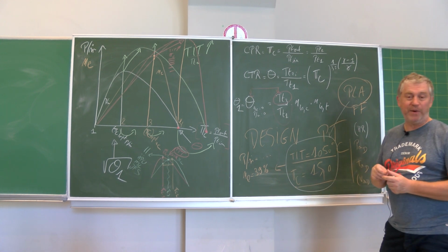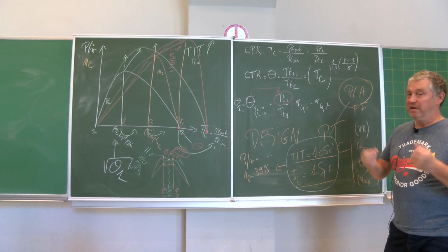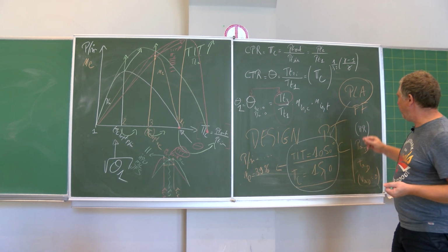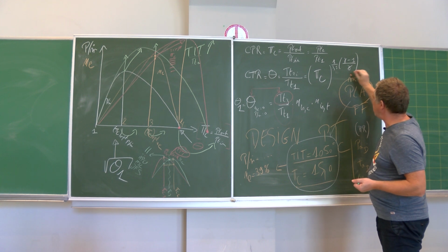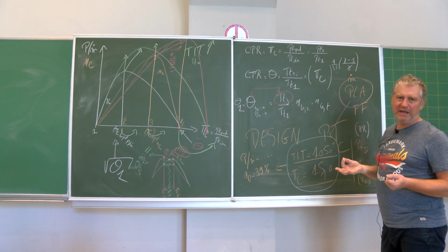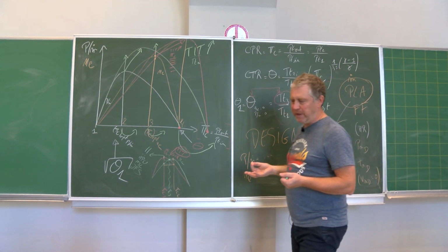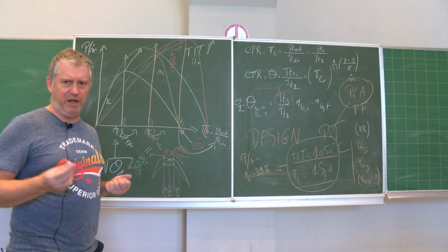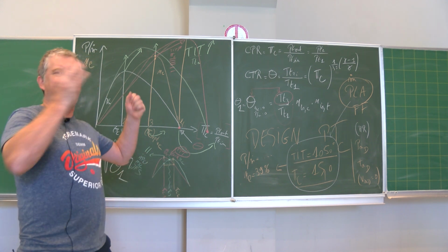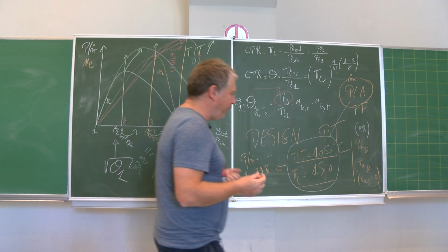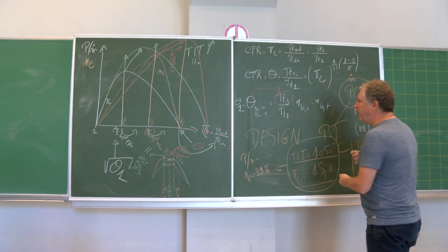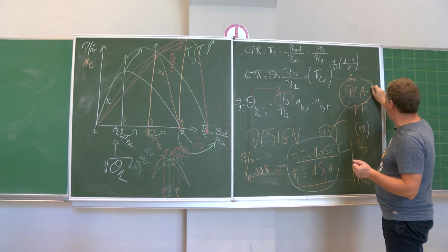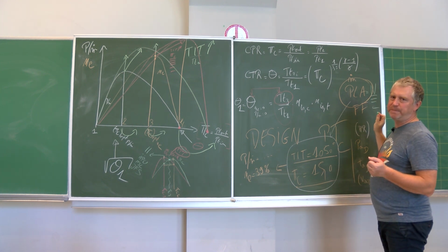It can be the pressure ratio when you have selected a certain compressor, and it can be a lot of other things. For example, it can also be related to the mass flow rate entering the engine. Because when you change the position of the throttle, you inject more fuel into the system, and everything is changing. And very often, we will characterize the PLA, I write it with an equal sign, with the rotational speed.